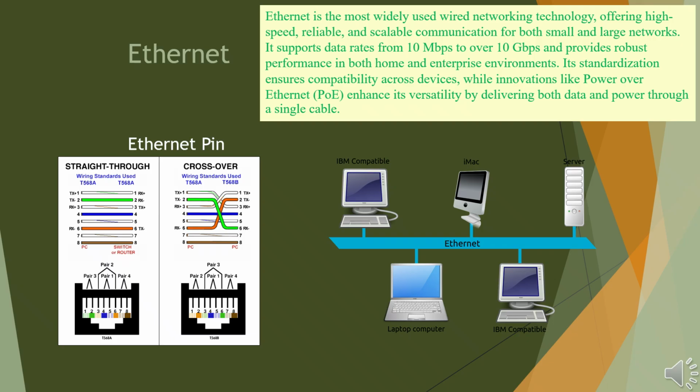In mechatronics and automation, Ethernet plays a key role in industrial networking protocols such as EtherCAT, Modbus TCP, and Profinet, which provide deterministic, real-time communication between controllers and actuators. These systems extend Ethernet's capabilities to meet the stringent timing and safety requirements of industrial environments. In summary, Ethernet combines high speed, long distance, scalability, and robustness in one universal communication standard. It's not just for office computers, it's the foundation of modern connected systems, from industrial robots to smart agriculture and IoT networks.